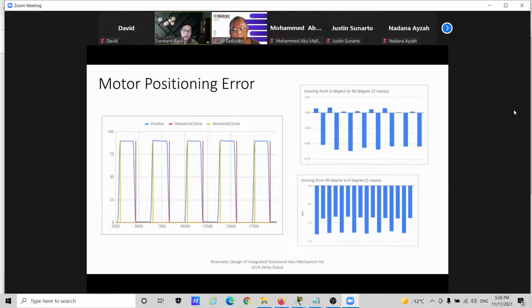Now this will be further, obviously much better once we get to aluminum pieces and metal CNC machine members of the linkages rather than a 3D printer. So we believe a combination of the PID tuning of the servo as well as some better machine kinematic linkage will reduce this error very significantly.